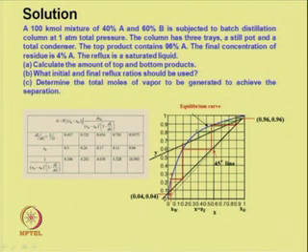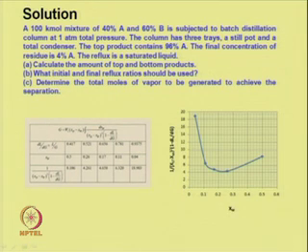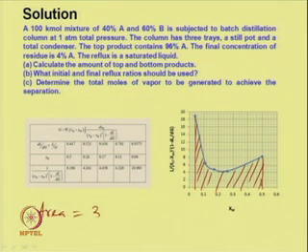With this we can plot 1 by (x_d minus x_W) squared into 1 minus dL by dG versus x_W. So, we can calculate the area under the curve for this integral. The area under the curve for this integral is this. So, this area is around 3.